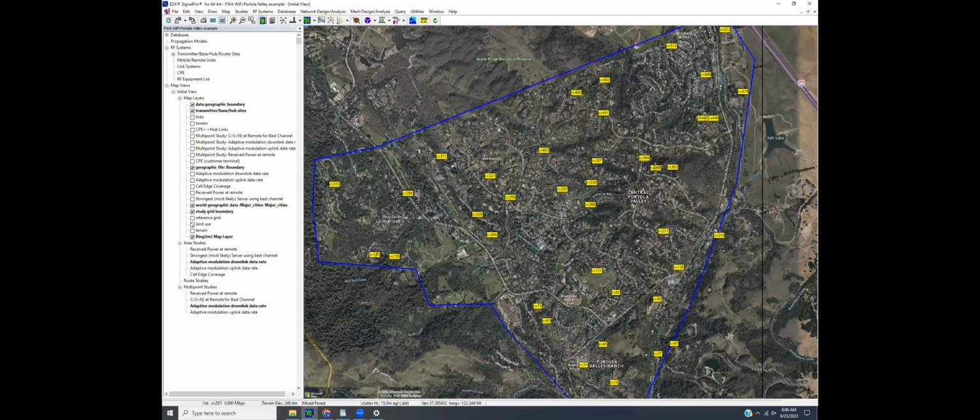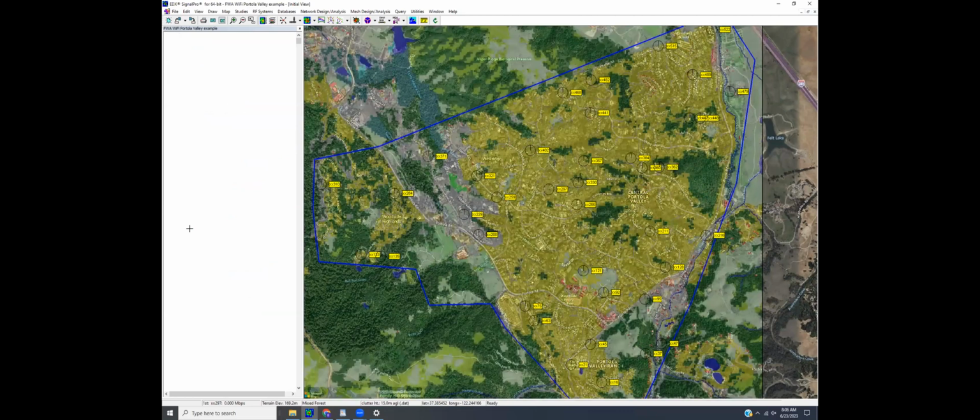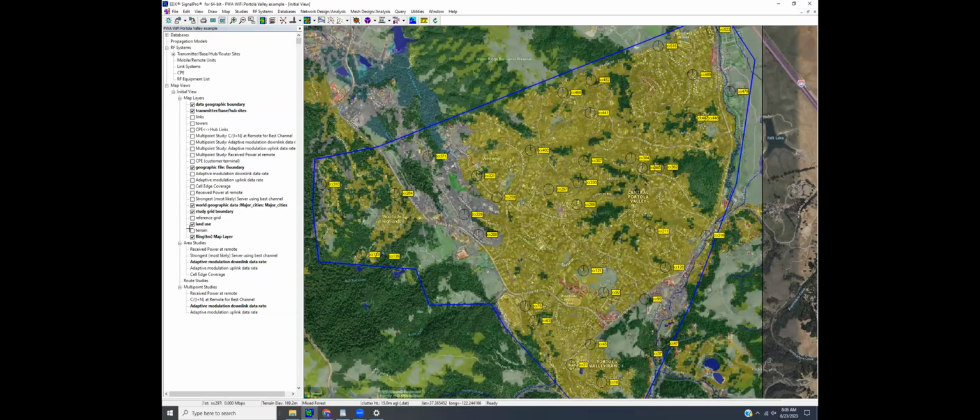And the first thing I always want to mention for that use case is the availability of really high resolution and high detail land use and land cover data. What I'm using right now is just our regular 5-meter subscription data, which is a 2D data set. But I could do my initial dimensioning of the project, for example, do some estimates with this data. And then if I won that project, I might seriously consider getting some custom clutter data with measured clutter heights, which is now available at a variety of resolutions for really cheaper than it's ever been.